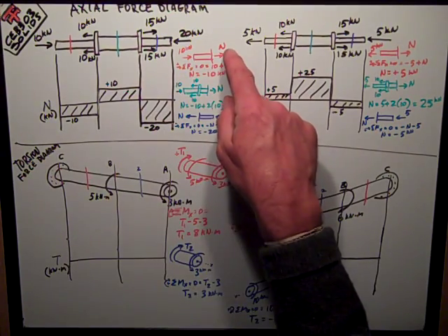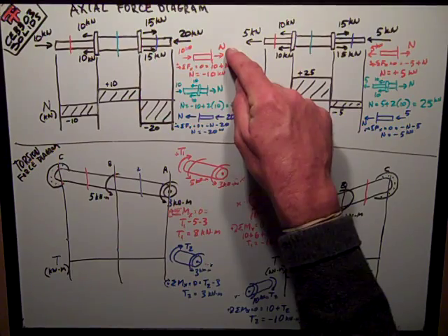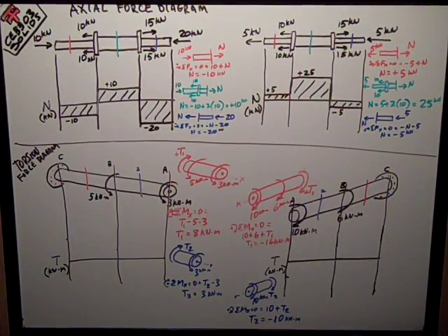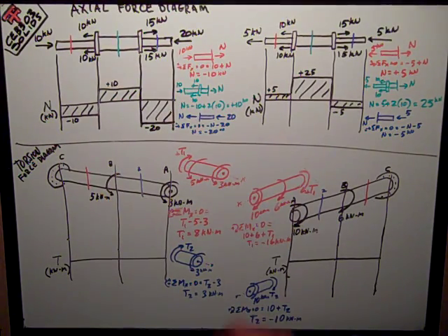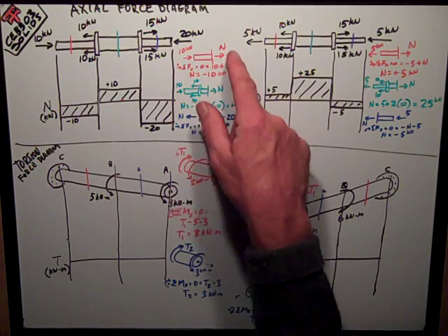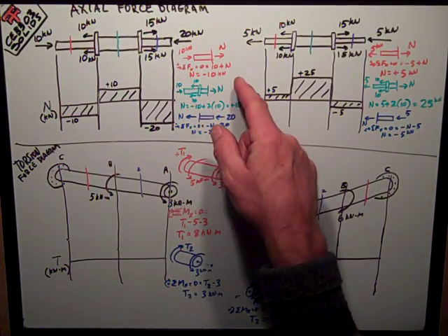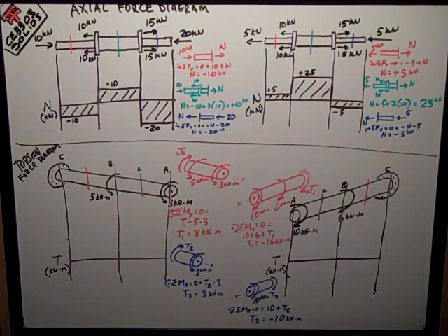Note that I want to assume positive for my internal force reaction N, so positive being tension in axial force. So I just assume tension positive and let the sign of my answer tell me whether I've got compression or tension.